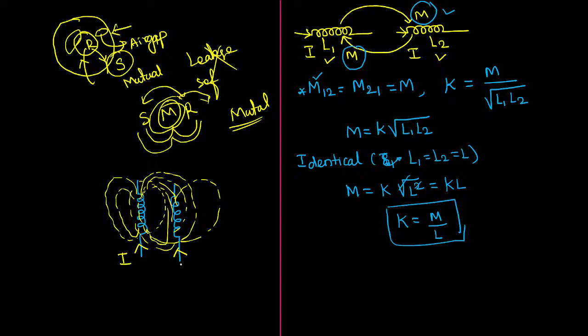Now the question is, if you observe, in both cases I am passing the current from bottom to top, right? It is going from low level to high level. In both cases, the direction of the current remains the same. When you pass the current through the two coils in the same direction, what will happen? The resultant flux produced by them will attract each other. So the first coil will try to pull the secondary coil close to the first coil.